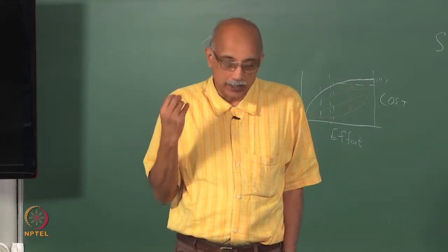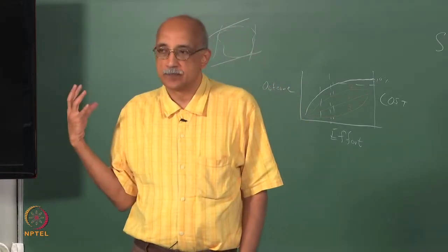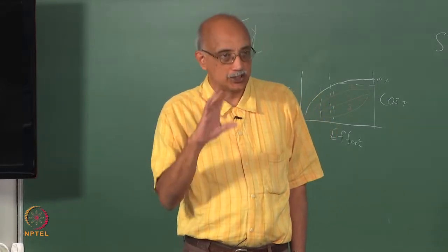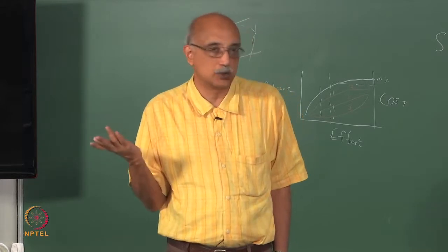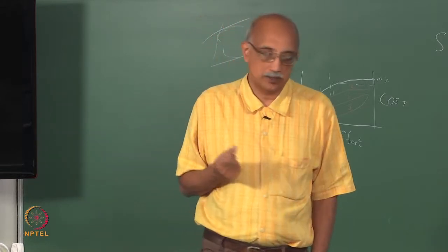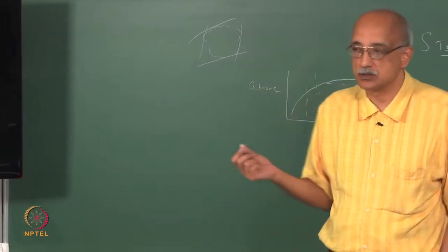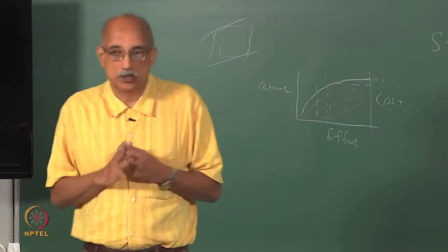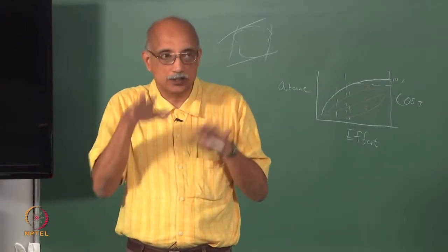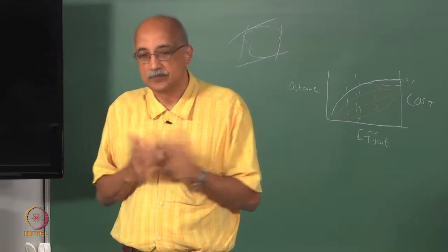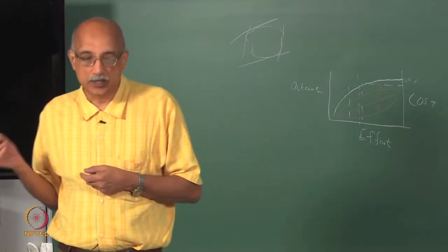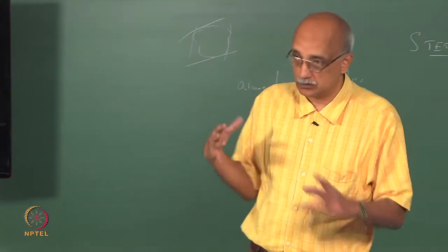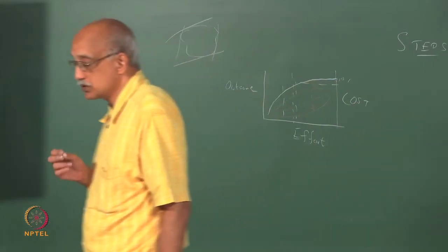So, if you have perfectly spherical particles, even before tapping they would have settled in a reasonable way. So, the ratio of before to after would be close to 1, whereas if you had initially a population of highly non-spherical particles, the way they fit into each other would be highly non-uniform, and many particles would tend to settle when you do the tapping, right. So, that is an example of a functional measurement of shape distribution in a particle population versus trying to measure each particle separately.